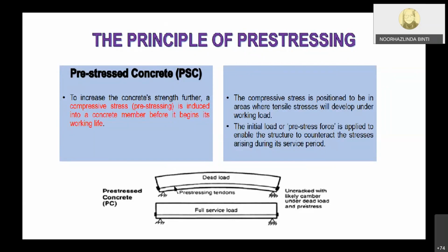Different from RC. In RC, you embed the reinforcement or steel bar inside that concrete. But for prestressed concrete, we are actually introducing compressive stress inside that concrete member before that structure is used for its service period.